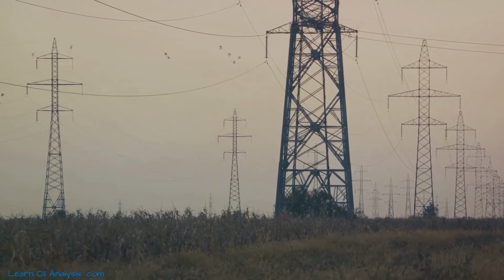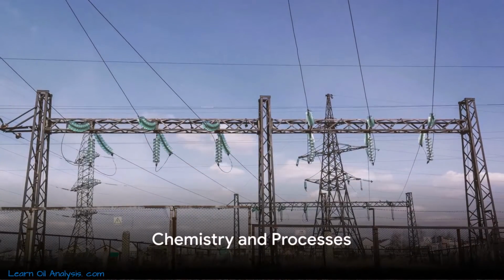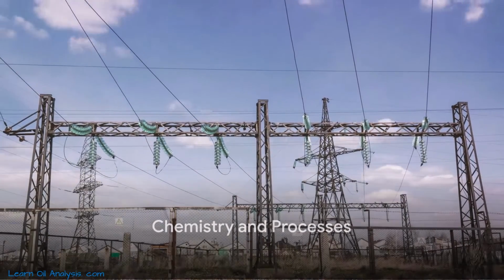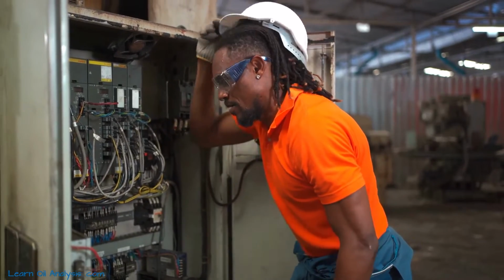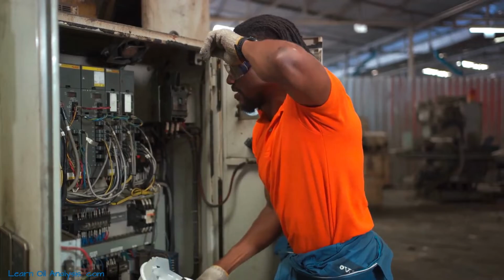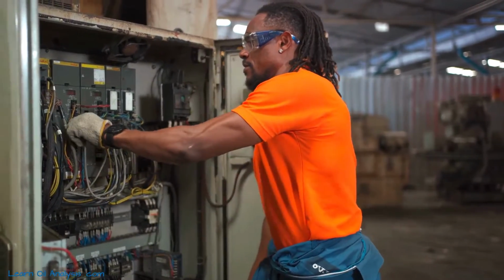High-energy discharges, involving extensive damage, are indicated by high levels of carbonization. Now that we've identified the key gases, let's explore the chemistry behind their formation. The processes leading to gas formation within transformers are fascinating and integral to our understanding of how each gas can be a telltale sign of specific faults.